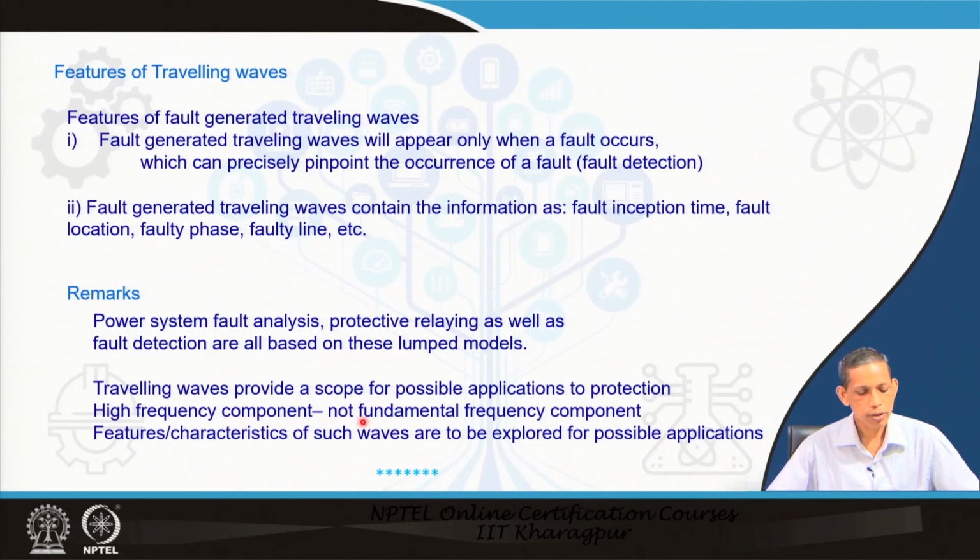High frequency component, non-fundamental frequency component. To get the high frequency travelling wave, we have to use a high sampling rate, and the fundamental component and other components are to be eliminated. Feature characteristics of such waves are to be explored for possible applications.